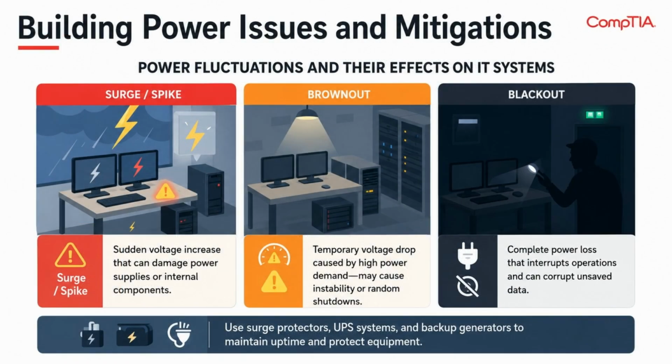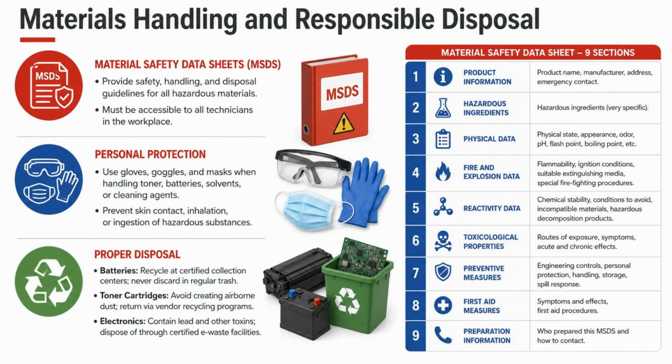Here's what an actual UPS unit looks like connected in a server room. Notice how it sits between the wall outlet and the critical equipment, ready to bridge any power interruption. Material safety datasheets provide safety, handling, and disposal guidelines for hazardous materials and must be accessible to all technicians. Personal protection means gloves, goggles, and masks when handling toner, batteries, solvents, or cleaning agents, preventing skin contact, inhalation, or ingestion. For proper disposal, recycle batteries at certified collection centers, never in regular trash.